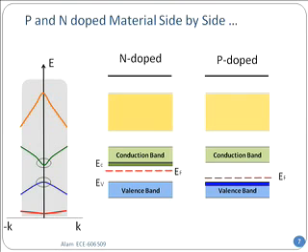Actually, nothing will happen, because of these surface states that we talked about. There are actually in every material lots of surface states. And when you bring the two materials together, the surface states will eat up all the extra electrons. There will be no electron transfer from one side to another. That is why you cannot simply bring an N material and a P material and sandwich them together to get a p-n junction diode. That's not that easy. Then it would have been done many years ago.